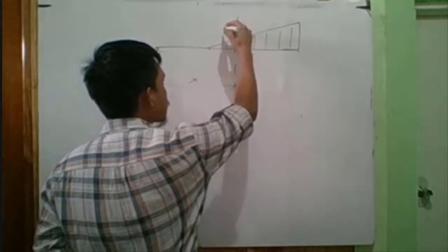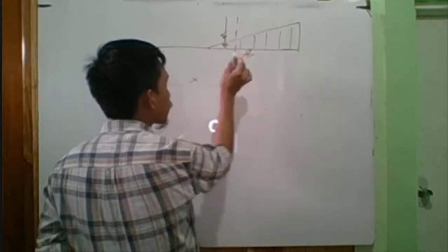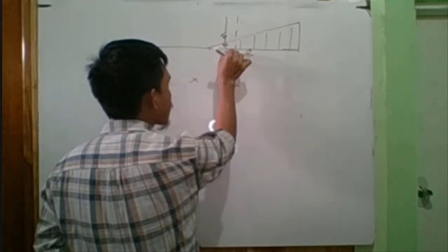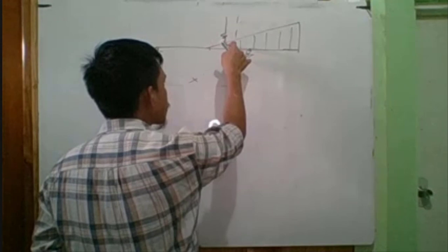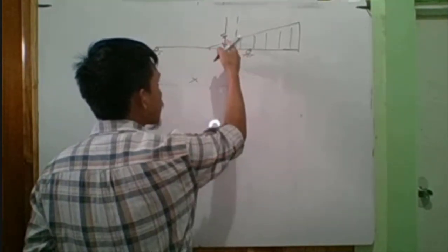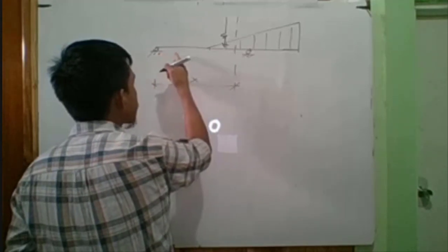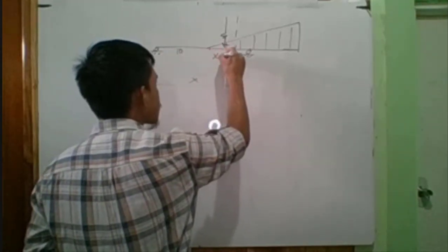And I want to include this one, so I need to get the resultant of that, which is located at 1/3 from this base of the triangle. Okay, so that is the location of the concentrated resultant of this distributed load. So again, I need to get the value of this so that I will take the moment of that. And then of course, if that is 10, this is 10. And then this is x, then that is x minus 10.